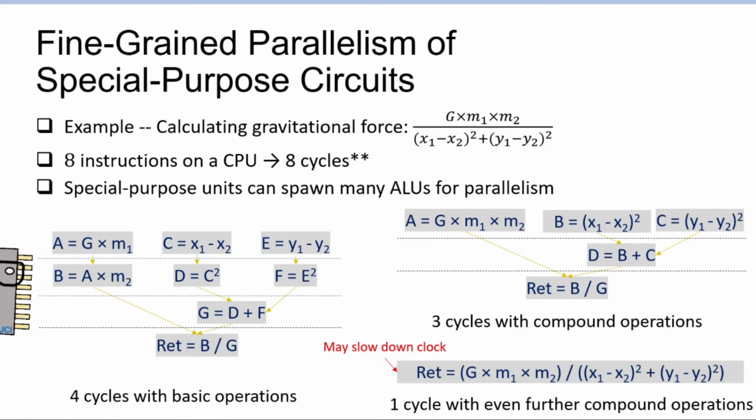So it'll take 1, 2, 3, 4 clock cycles, depending on the breakdown of the dependencies. But the bottom line, it will take 4 cycles of latency, but because it will be completely pipelined, if you remember, the pipelining aspect was described in undergrad computer architecture. These 4 stages will be completely pipelined, meaning even though the latency of this operation is 4 cycles, you can